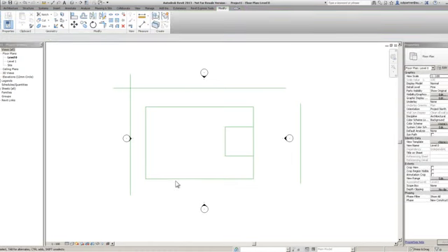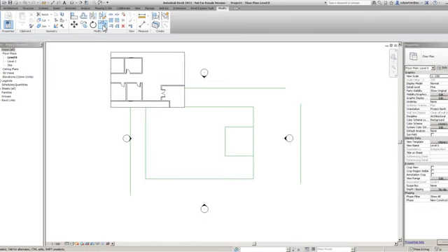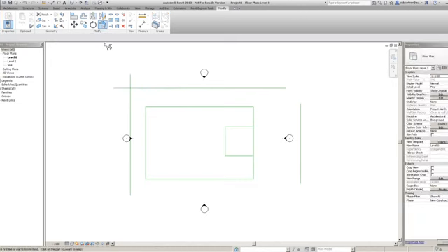Now, what we're going to do is have a look at our different trim commands. They're up here. I've stayed on the modify command so that I can do it quite regularly. I'm going to hit this one first. This is a tool we use absolutely loads in Revit. It's basically Trim/Extend to Corner. It works very similar to the fillet or chamfer with a 0 radius or 0 distance in AutoCAD.